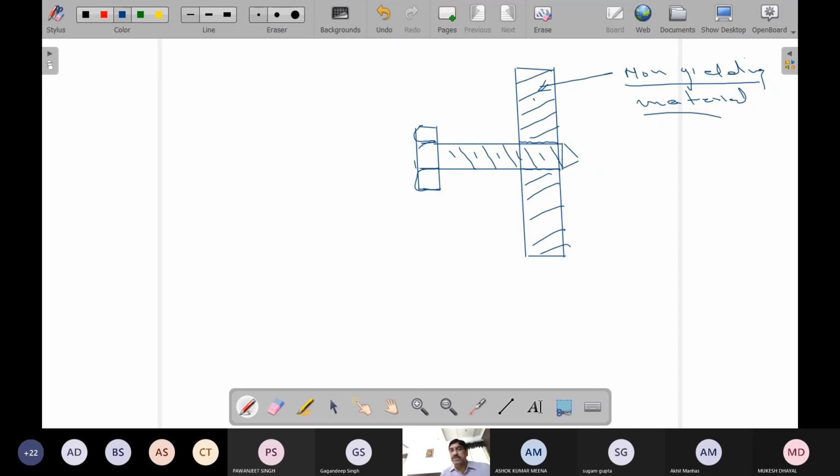And therefore, every time I do the same thing, I turn by one revolution. Let us say 2.2 millimeter is the pitch. If I turn one complete revolution, it will move 2.2 millimeter. If I turn it 2 revolutions, it will move 2.2 into 2. If I give 3 revolutions, 2.2 into 3, and so forth. And every revolution will positively give me the same distance traveled. The reason is it is in a medium which is non-yielding. Now the screw propeller, the propeller on our ship, is also based on the same principle.